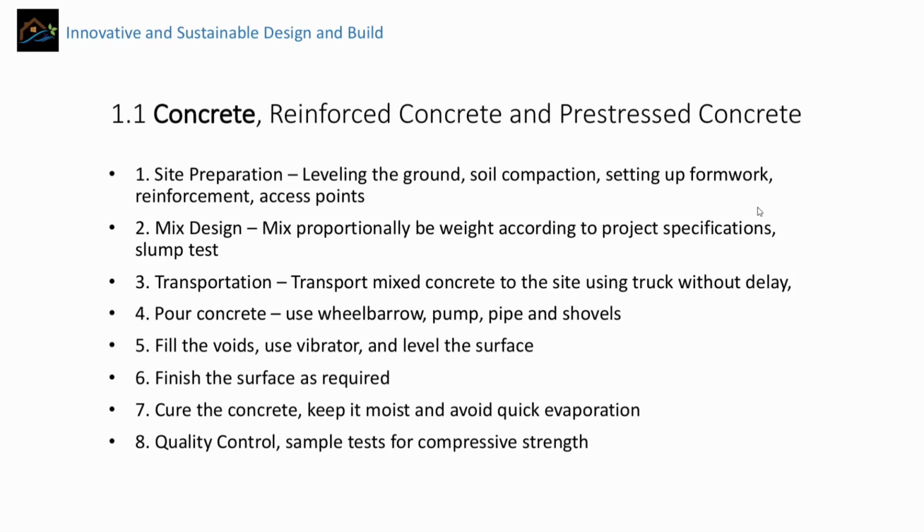After we are done with the finishing, we cure the concrete, trying to keep it moist and also avoid evaporation. During this time, we also do quality control to check whether our poured concrete has the desired specifications, the desired compressive strength.